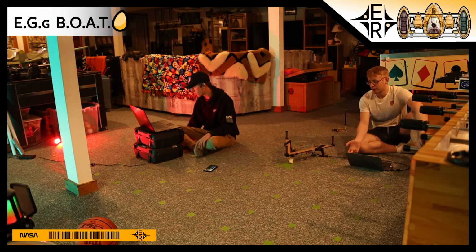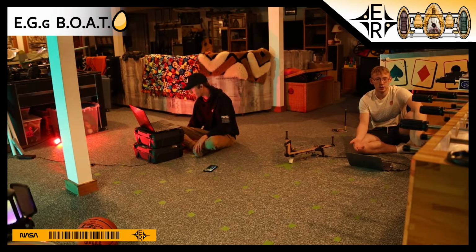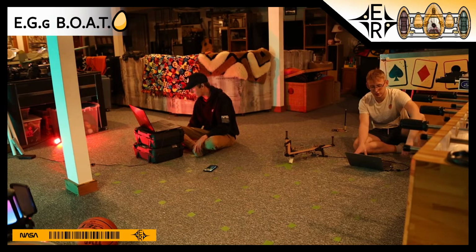But at extremely high frequencies, the component values aren't just the rated values. Parasitics start to factor in. The shape of the board itself starts to factor in. So nothing was working as intended, and that took a lot of testing and different prototype versions to eventually get the filters working.